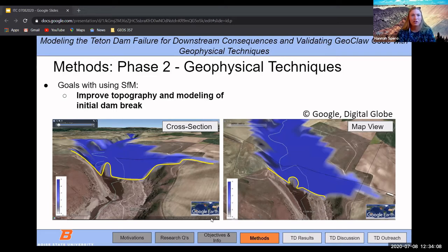Additionally, as you can see in these images, there is a flat wall of water that is waiting to be released. Like the HEC-RAS model of 1977, we made the assumption that the dam breach developed instantaneously and completely. As the storage area elevation drops to the topographic elevation, that's when the floodwaters are released. So if we had a higher resolution of the initial dam, we would be able to implement smaller variable steps and we could potentially do a gradual dam failure, which is one of the goals we are working towards.